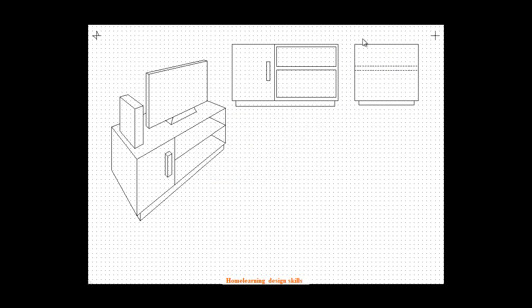So now if you're drawing from the inside of things, you can see where the plinth would be. Okay, so that's that part going through. I suppose the other thing that you may see is the back of the unit as well. So if I just turn off my grid lock for a second, you'd see the back, if we're looking at the inside of it, and you'll also see the top and the bottom. So whatever these lines are here, I'm just going to take these across, and wherever that line is, take that across, and it's starting to add just a little bit more detail than we did last week. So now we're using dashed lines to show hidden features.